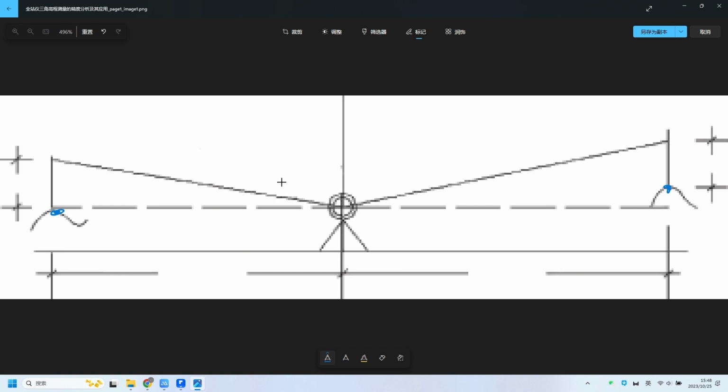What does it mean to set up stations at intervals? Some of our friends may be accustomed to using the middle method, which means that when we measure at 2 target points, we do not call them any points, but rather 2 targets. We directly set up our prism on these 2 targets, a fixed height prism, and our total station we can set up at any place, not at a control point, but at any place where we can see both targets simultaneously.